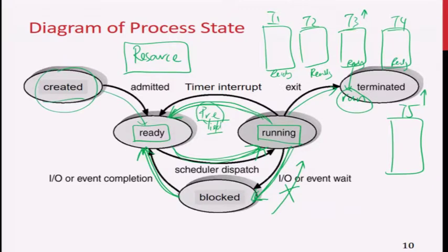So that is why sometimes when something important happens, you press the camera button, you want to take a picture, and the screen doesn't want to come up. You are waiting, and you only see the black screen. You cannot take a picture. Why? Because something else happened. Some other higher priority task happened, or your task got blocked. Something prevented your task from going from ready to running state.